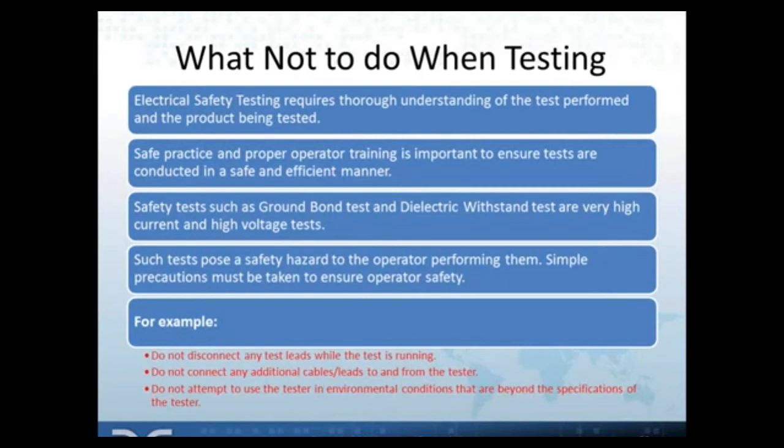Again, do not connect any additional cables and leads to and from the tester when the test is running. So when the test is running, you should know which cables and which test leads should be connected. If you don't know that, do not attempt to perform the test, because that can lead to a safety hazard for the operator, and it can damage the tester and the device and your product that you're trying to test. Also, for those of you who already use our testers, we highly encourage you to make full use of the manual and all the literature that's provided with the tester.